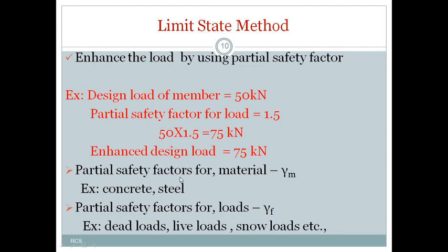Right. The partial safety factors for materials are generally represented with gamma m. As we are designing RCC elements, in RCC elements we are using materials like concrete and steel. The material factor of safety is represented in terms of gamma m, and similarly the partial safety factor for loads is represented with gamma f. Generally those loads are dead loads, live loads and snow loads. While designing these design loads, we will consider a combination of all these loads.